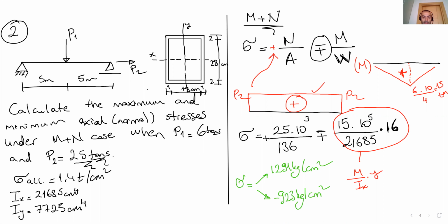So we check this stress as an absolute value with the allowable stress. So both stresses are less than allowable stress, and the section works under this loading condition.